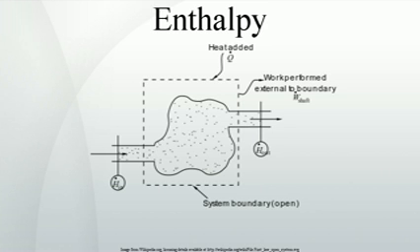The terms represent enthalpy flows, which can be written with the mass flow and the molar flow at position k respectively. The term dV_k/dt represents the rate of change of the system volume at position k that results in PV power done by the system. The parameter P represents all other forms of power done by the system such as shaft power, but it can also be for example electric power produced by an electrical power plant.